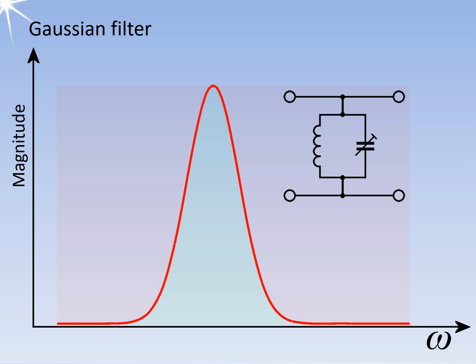In electronics and signal processing, particularly in digital signal processing, a Gaussian filter is a type of filter whose impulse response is an approximation to a Gaussian function. Gaussian filters possess some remarkable properties, such as having no overshoot to a step function input while minimizing the rise and fall time. This behavior is closely related to the fact that the Gaussian filter has the minimum possible group delay. Consequently, a Gaussian filter can effectively suppress high frequencies while simultaneously minimizing spatial spread, making it the critical point of the uncertainty principle.